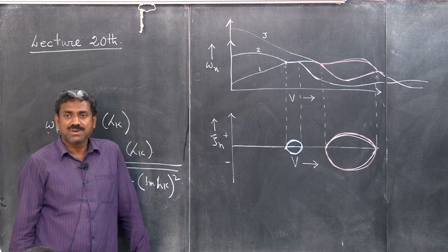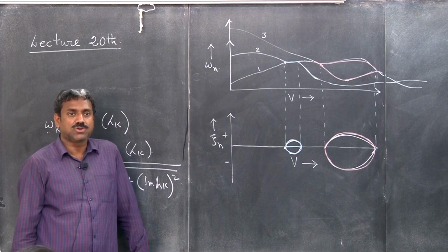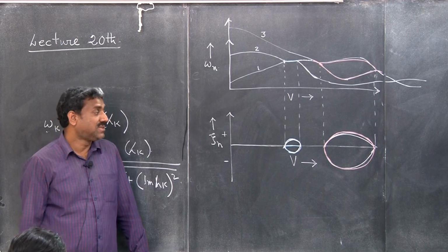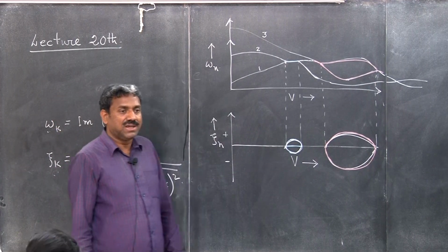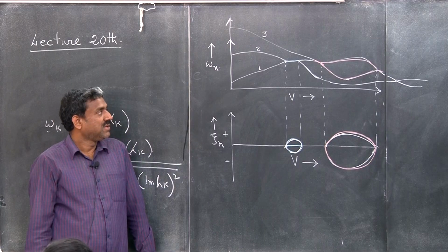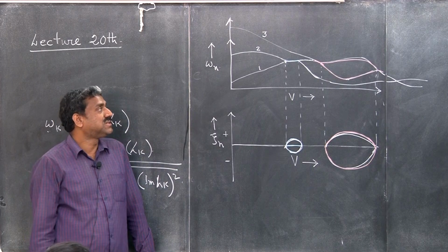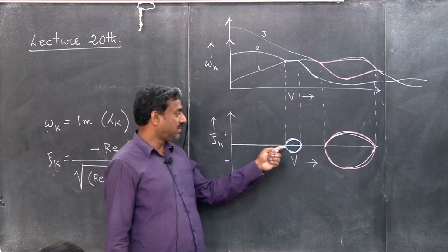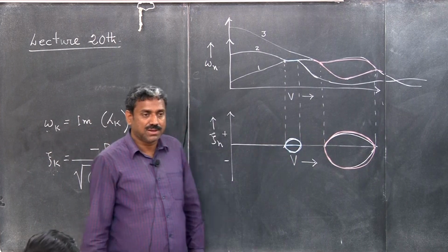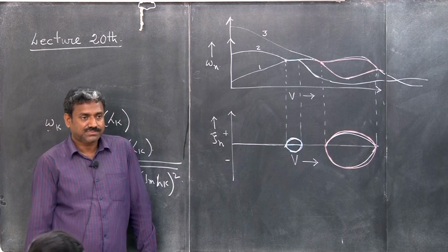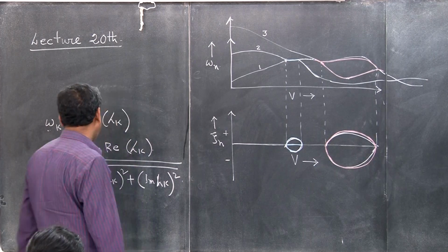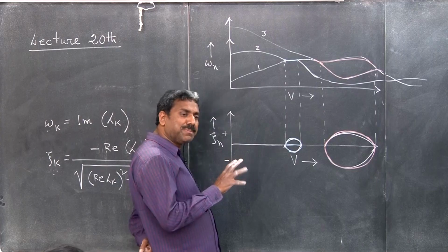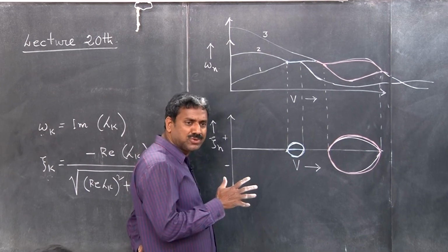Which parameter? The parameter which is controlling the stability behavior. For this case it is the wind speed, right? So I hope you understand why the frequencies are coalescing and why they are bifurcating, okay, and why they are projecting, and there you can say this circular kind of shape is coming, right? Clear? Please note that they are appearing in pairs, complex conjugates, right?